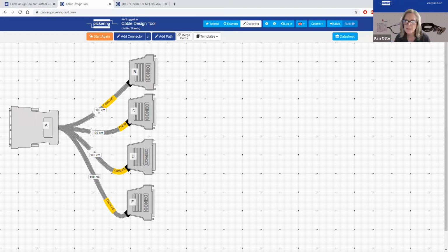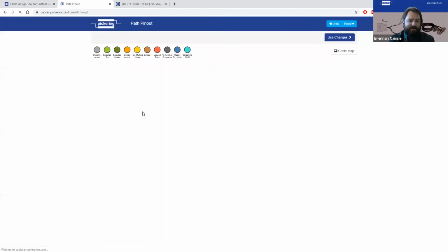How do you handle the screen on a twisted pair screen cable? Typically, the screen must attach to the back shell. Sure. When we do these cable designs for cables that have an exterior screen, those will be connected to the back shell of the connectors. We can go back into this link pin option as well and just take a look here.